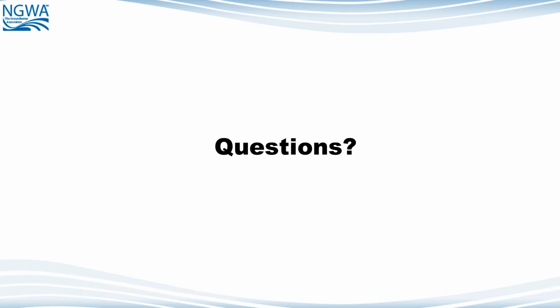That's a good question, and unfortunately some of the media has indicated that in Flint these were carbon filters that were, they did qualify that by saying they met NSF drinking water standards. There is a standard by NSF called Standard 53, which is designed to qualify a device to filter out a health-related contaminant.